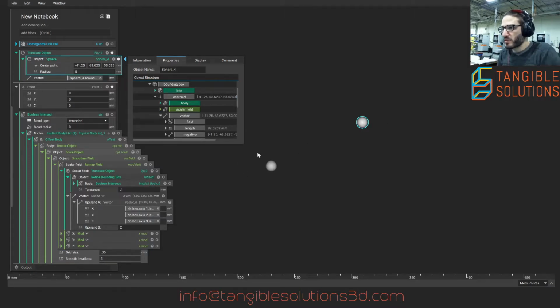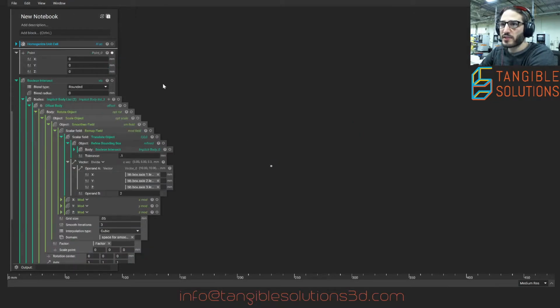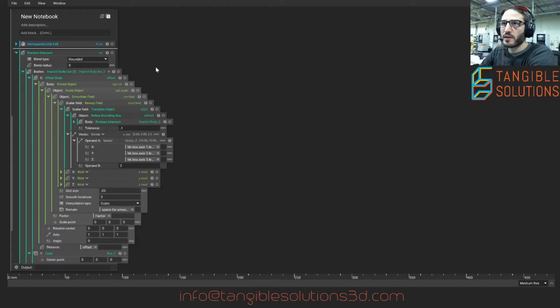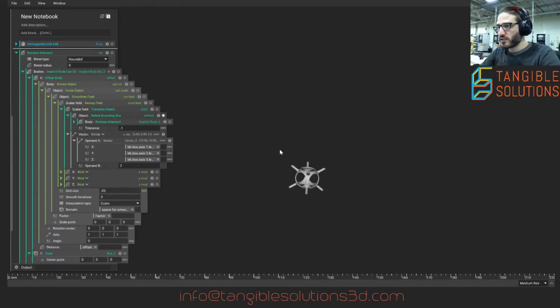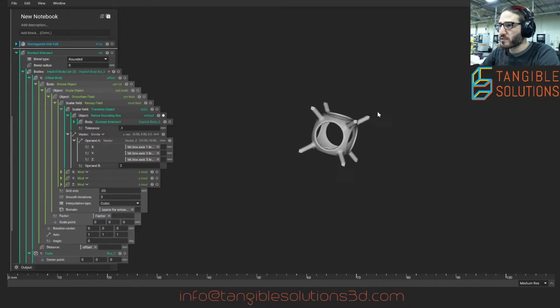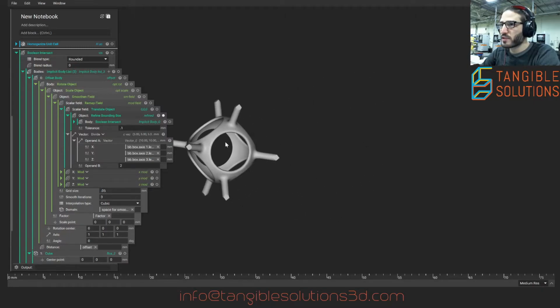I usually do this. This is a trick that I do with meshes, right? Sometimes meshes come in way off somewhere in space, so a good way to get them back to center is to find the vector of their centroid and grab its negative, and it pulls them back into the global origin. Again, this just allows you to be operating inside nTopology's origin, which I always find a little bit easier. It's also easier to scale, view, and rotate if you're centered at 0.